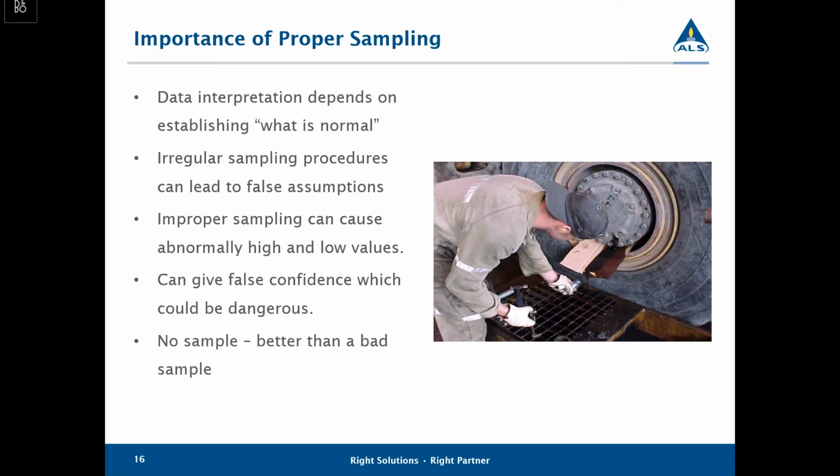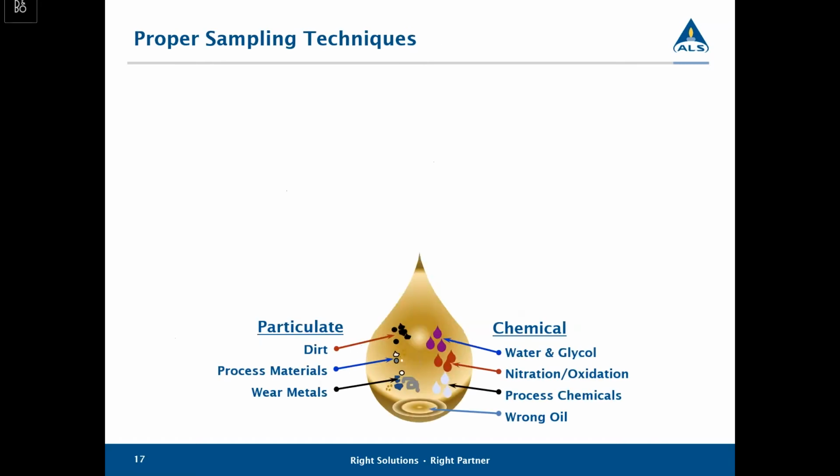In reality, no sample is better than a bad sample. And it really comes back to that false confidence. We really don't want somebody to get a report that looks good because it was a bad sample and give that false confidence. If you can't take a good sample, don't take one at all. Do what you can to take a good sample. If you have to take it at a different time, a different day, you have to change your schedule for maintenance, and it's very important that you get a sample done right. Do that. Don't sacrifice trying to rush getting a sample just to get one, because if it's not a good representative sample, it's worthless. You've wasted your time.